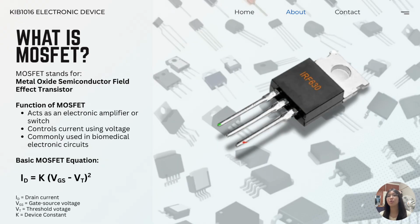And now, let us look at the MOSFET. MOSFET stands for Metal Oxide Semiconductor Field Effect Transistor. It is an electronic device commonly used for amplification and switching in electronic circuits. Unlike a BJT, a MOSFET is voltage controlled, meaning that a small voltage applied at the gate terminal can control a large current flow between the drain and source terminals.